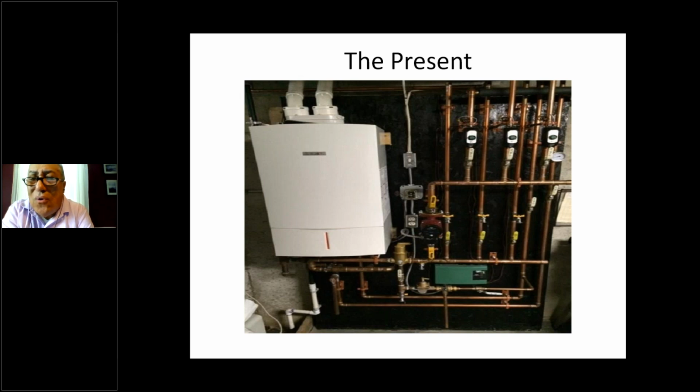One of the things you were doing when you opened that door was you gave that fire a big gulp of oxygen, which made the fire actually pretty good. It was a really nice looking fire. Of course, as soon as you closed the door, it went back to having smoke, which you couldn't see. So opening the door was very counterproductive. Boilers today don't have doors. You can't open the doors. There's nothing to see, which is a good thing, which really shows the need for testing because you can't see anything.